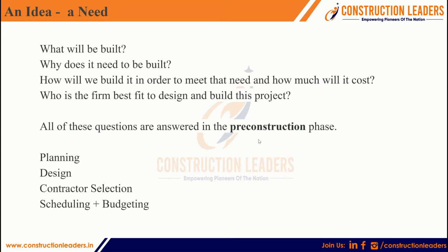And an idea, a need. In general, we talked about it, right? Everything should start from the idea. Everything started from the idea. And what will be built? Why does it need to be built? How will it be built in order to meet the need, and how much will it cost? Who is the firm best fit to design and build this project? All of these questions are answered in the pre-construction phase. It is a very important one. And in this phase, the following activities will be carried out: planning, designing, contractor selection, scheduling, plus budgeting.